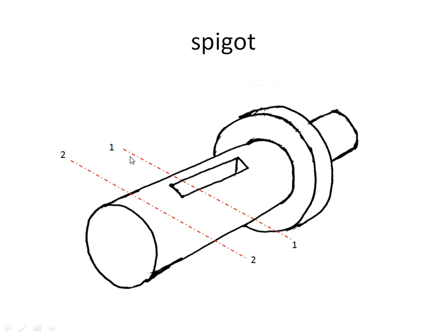The tensile stress induced in any component acts on its cross-sectional area. The next type of stress is shear stress. The spigot and socket are subjected to double shear stress. The shear stress developed in the spigot is in the portion from the slot end to the spigot end, which is indicated by small letter A, and in the diameter of the spigot.